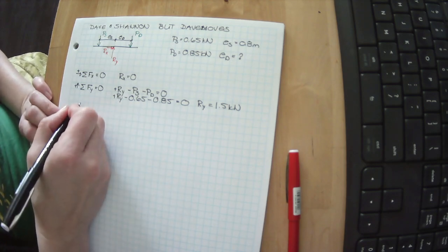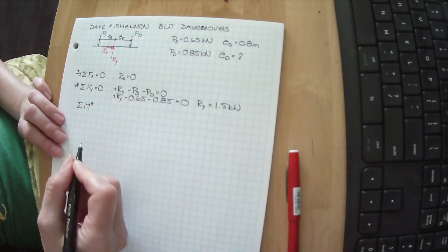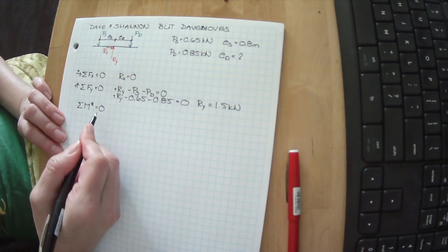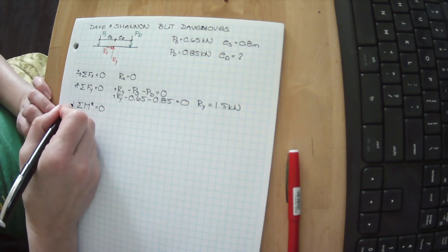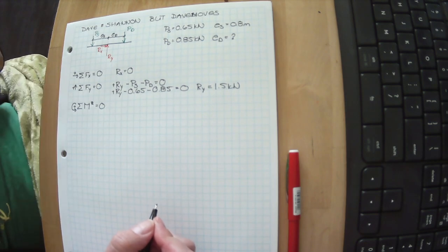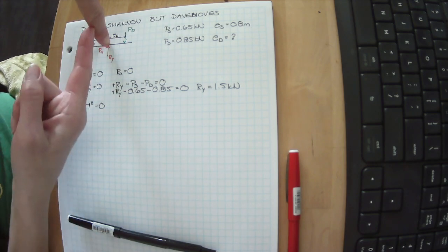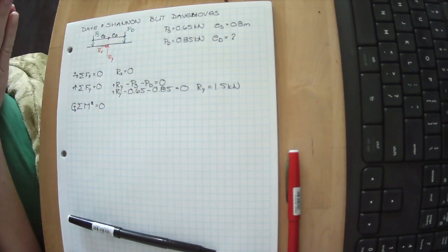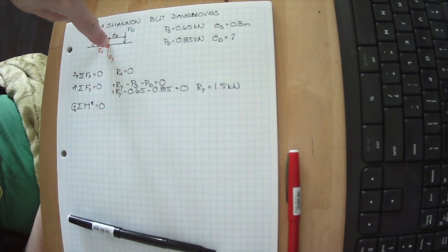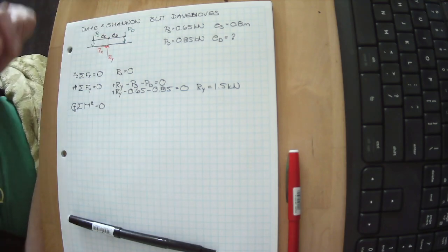And there's a third part to making sure this is in static equilibrium. We want to sum all the moments about the z-axis, and we want it to be in static equilibrium, so the sum of all of those needs to be 0, meaning it's not rotating. And everything in that direction is positive. So let's see. We've got our thumbtack right here. Our y doesn't cause it to spin. To be a moment, you need a force and an eccentricity. And if this is where a thumbtack is, our y isn't causing it to spin. Our x is passing through our thumbtack and isn't causing it to spin.